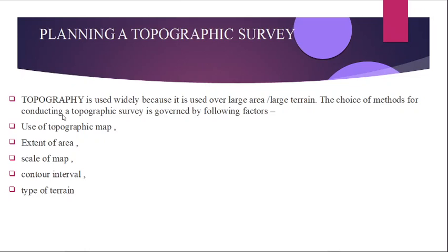On the other hand, for estimation of the storage capacity of a big reservoir, a small scale map may be used and the accuracy required may not be very high. Another example is a topographic survey for a bridge site. The topography in the vicinity of the river crossing should be represented more accurately than in the areas away from the crossing.